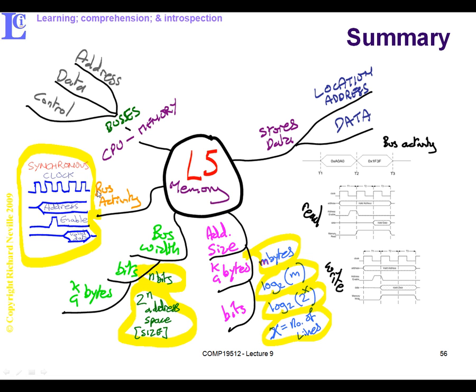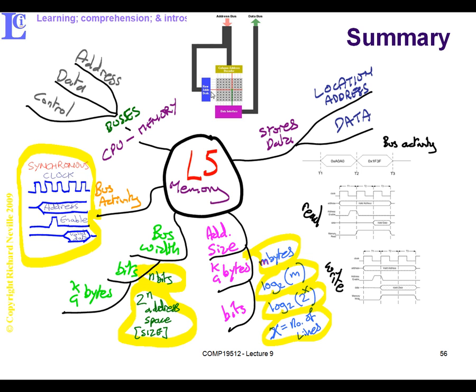Okay, and then we saw how synchronous RAMs can be used to read a number of bytes sequentially given a particular start address or base address, and then we clock them out every half clock cycle. And this was our diagram we used to depict reading and writing into an actual memory, a bit beyond the course, but you can see now why we've got CAS. Column address strobe will be this one, and that will be row address RAS.